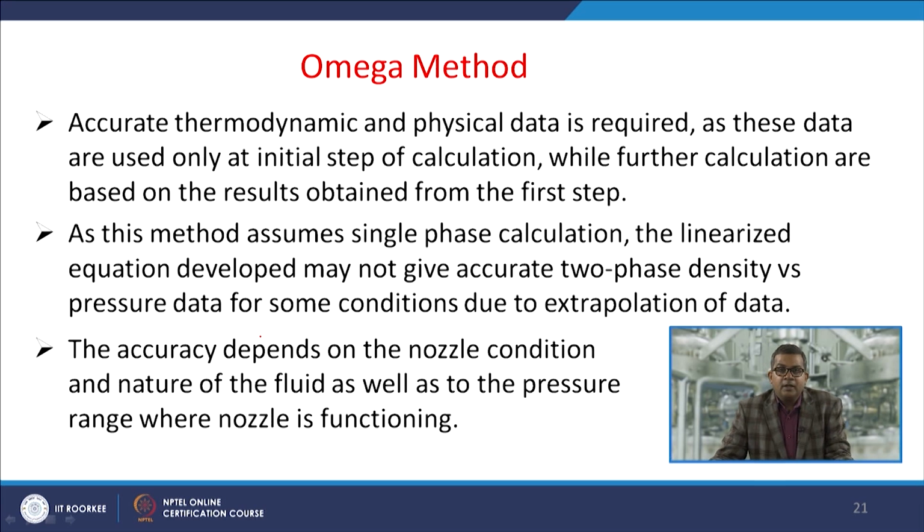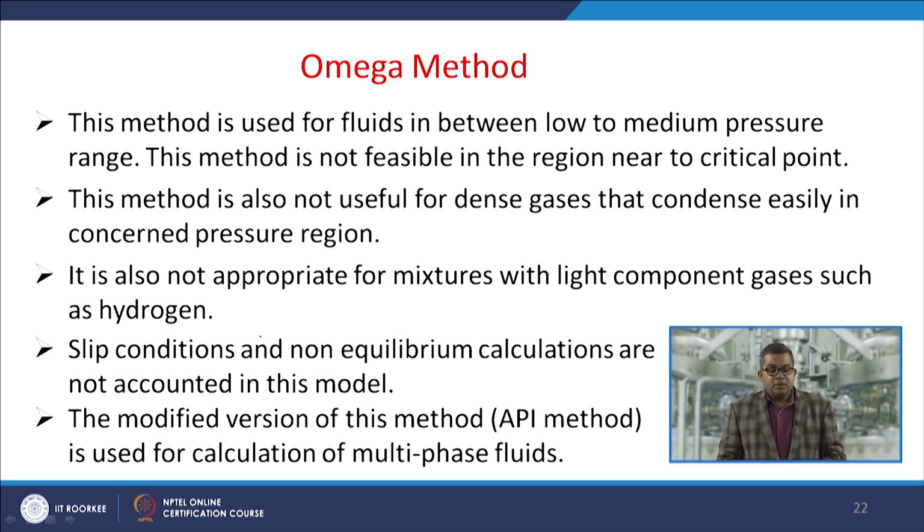previous slide. Now, as this method assumes a single-phase calculation, the linearized equation developed may not give accurate two-phase density versus pressure data for some conditions due to the extrapolation of the data. So, this is again a very important point. Now, the accuracy depends on the nozzle condition and nature of the fluid, as well as the pressure range where the nozzle is functioning. Now, this method is used for fluid in between low to medium pressure range.